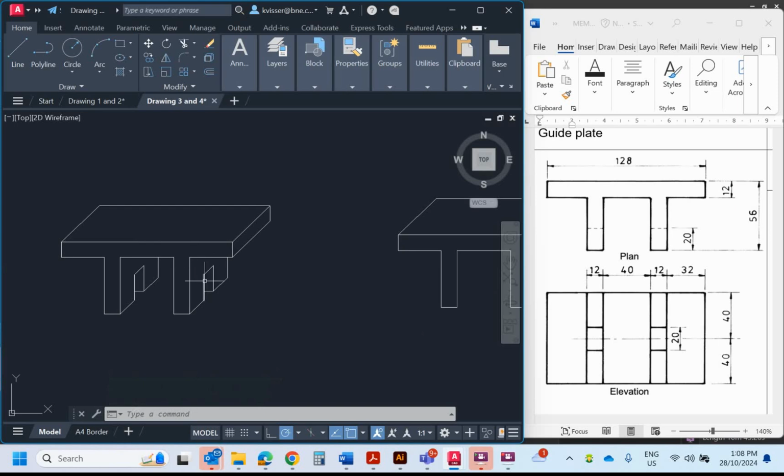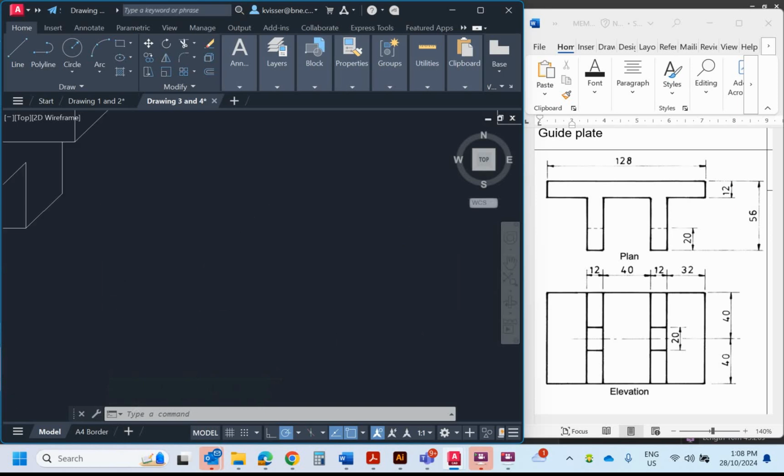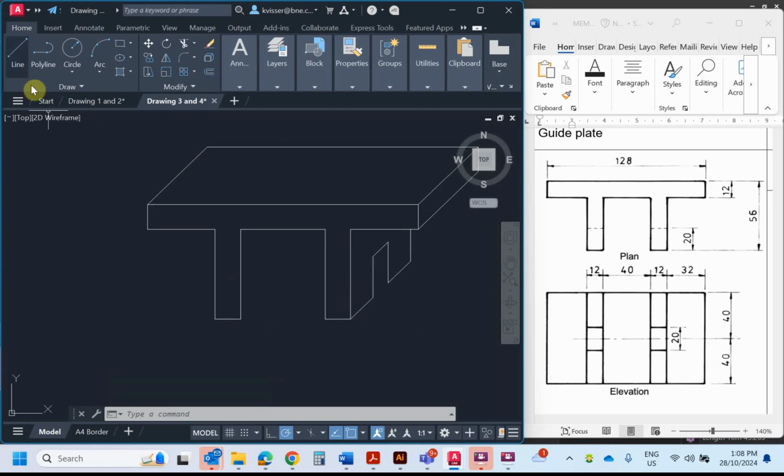Because this piece is going to be identical to that piece, I'm also going to do something else a little bit tricky. I'm going to finish it off first, and then I'll go CP for copy, spacebar, left clicking to create the lasso, and then left click again. So I read down the bottom, it says copy selected objects. Yep, no more to select, that's it.